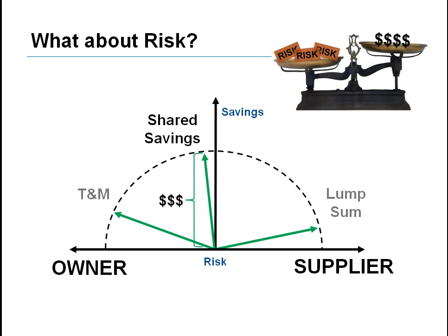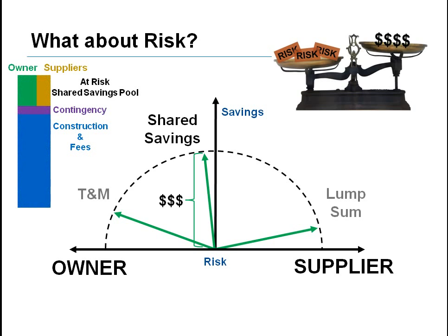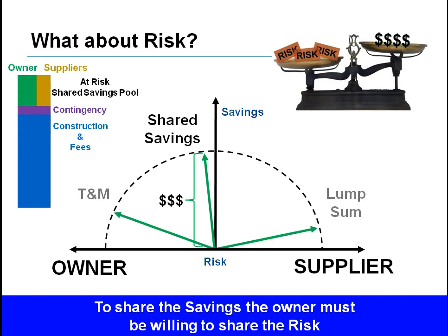The contract can take several forms ranging from the full integrated form of agreement, or IFOA, to design-build with the team sharing a common IPD team contingency for design and construction errors and other unexpected costs that would not result in a change order. IPD team members place their profit in an at-risk pool. If the project overruns the agreed-upon target cost, then cost overruns are funded from the at-risk pool first, then by the owner. The owner limits liability of risk pool members to the at-risk pool. Aggregate project savings are typically put into the pool.